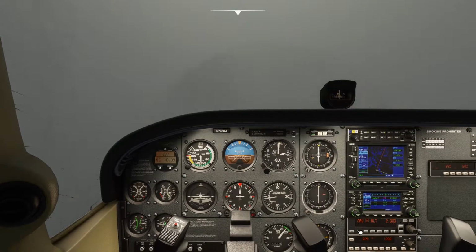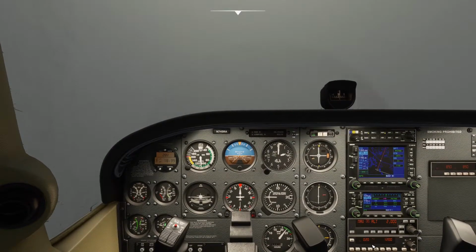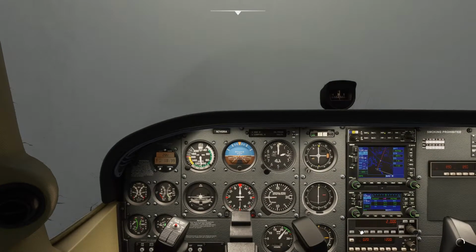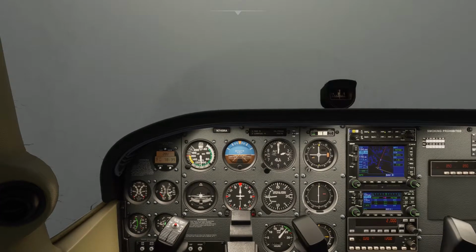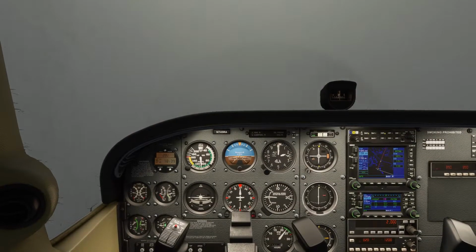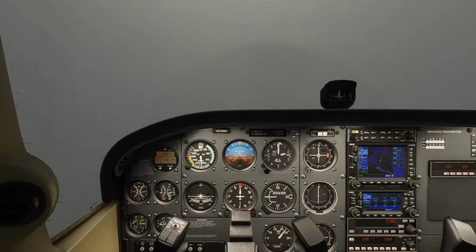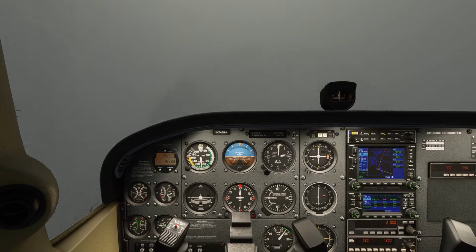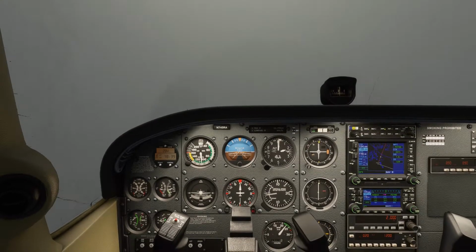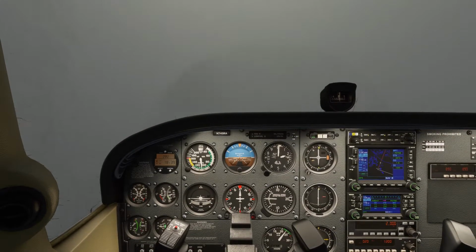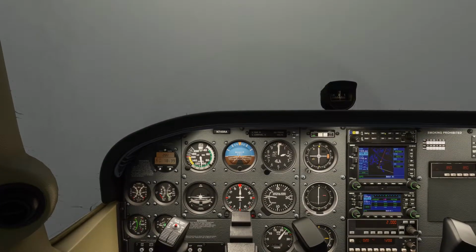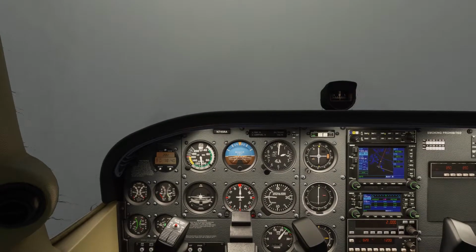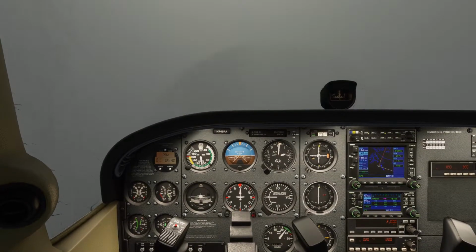Okay guys, so around about 2 miles to go to Petney now. I'm going to take the autopilot off and start flying manually because it's lazy. There we go, so the autopilot's now off, so I'm flying manually. So just keeping the scan going now, attitude indicator down to the DI, up to the attitude indicator, across the altimeter, back to the attitude indicator, across to the GPS. I'm checking that distance. I want to start that turn just before I get to Petney, because otherwise we'll end up flying over it and through the final approach track. So around about a mile before Petney is good to start that turn.